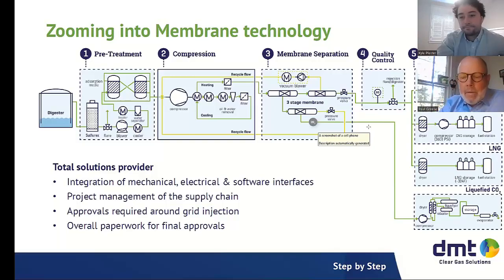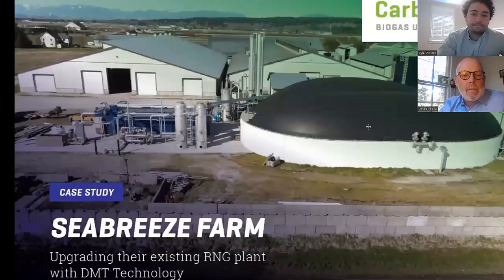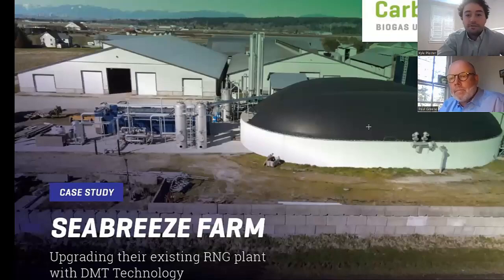So you have a bit of a case study we can go through here. Sounds good. Yeah, tell us about the Seabreeze Farm. Yes, so Seabreeze Farm is a facility up in British Columbia, Vancouver. It's interesting because it's half manure, but also half source separated organics. So it gives us a good mix of different feedstocks in the industry. Another thing that's interesting is there was an old water wash system here that we replaced. So it's no knock on water wash, but for this system, it being a small dairy farm, they realized that the best technology fitted for this product would probably be a membrane just because of the reliability.